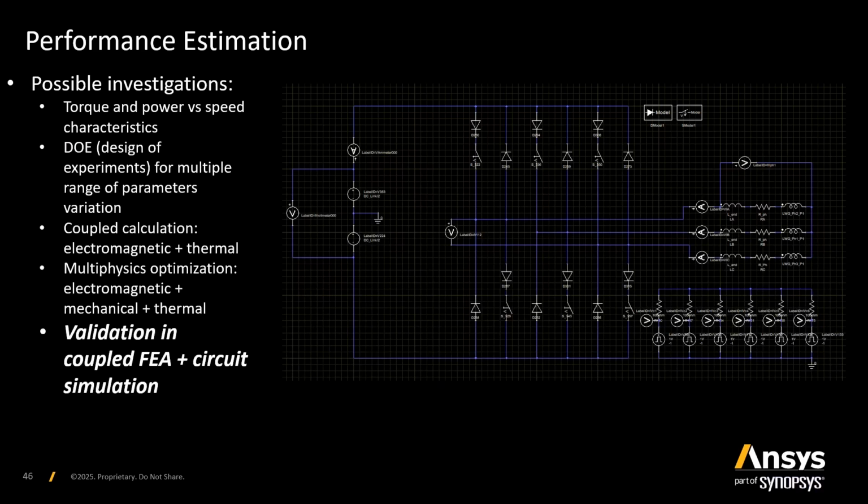Now, until now, we looked only at making use of a multi-physics approach in MotorCAD. However, we need to validate this performance using a more in-depth calculation, making use of Maxwell. Maxwell will allow us to do finite element analysis in 2D and 3D, and as well coupled to the dedicated circuit. This is done very easily through exporting. MotorCAD automatically generates a model that is scripted and can be imported directly into Maxwell. So we'll have the same geometry, the same material, the same supply.